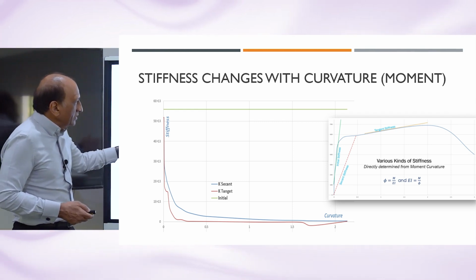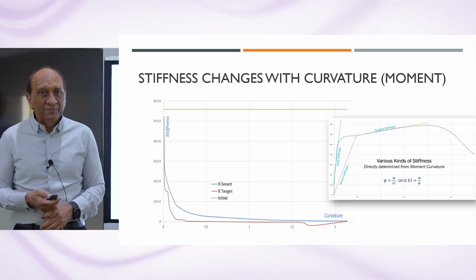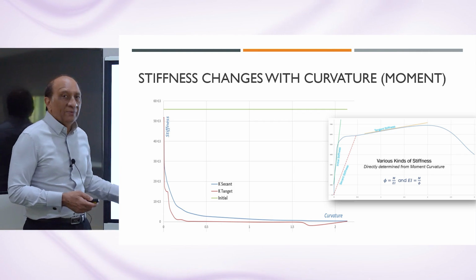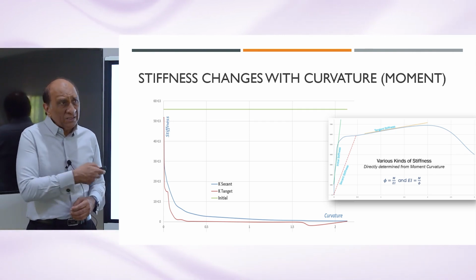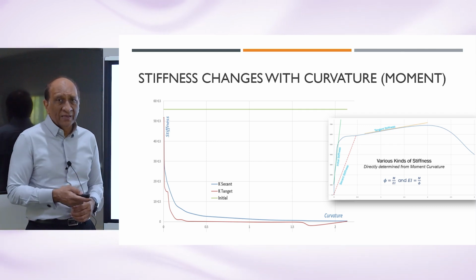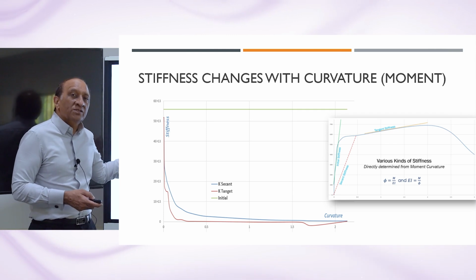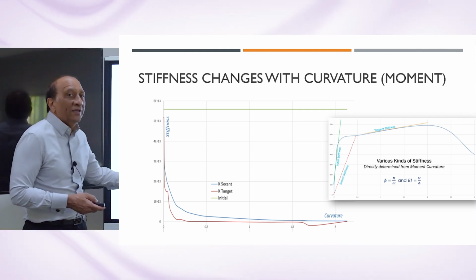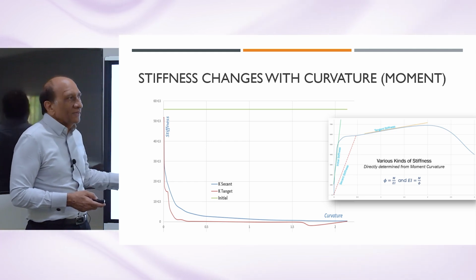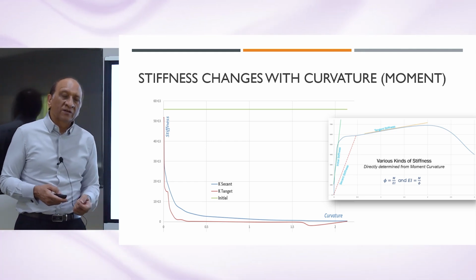The stiffness is a fraction of the initial stiffness, really a fraction, you can see, and it drops rapidly. But this plot can indicate that the stiffness determination, especially for beams without much axial load and without much reinforcement, will be like this. And this can be affected by many things, as we have discussed earlier. But this gives you an idea that the initial stiffness that we calculated, or the gross stiffness, has no real relationship or real insight into the actual stiffness after deformation.